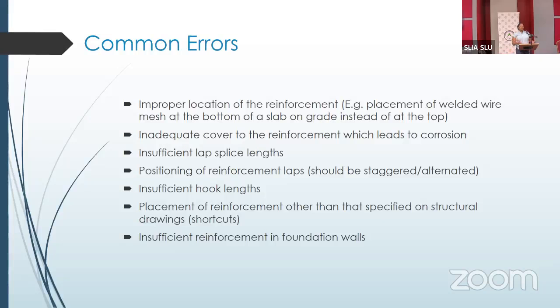When it comes to structural members, there's a minimum bar diameter that the code says that we need, which is basically a T12 or a 1/2-inch bar, high tensile bars. So those are things that we need to be aware of. If it's somebody who's not trained like the rest of us, they will gladly accept it. Or if they don't have somebody to guide them, they will gladly accept it. So the first thing that comes to my mind as an engineer is that that building needs to be retrofitted.